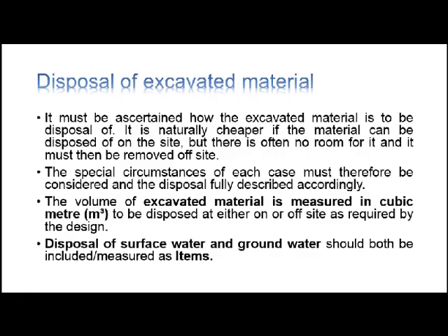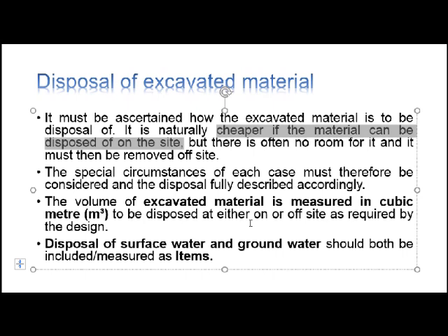So how about the disposal of the excavated material? This one relates to the trench just now. You should be certain how those excavated materials are to be disposed. Normally if you put it on site, it is much cheaper, but sometimes if there's no area to place that material, you might need to remove it offsite. That would cost you more. The rate would be different. If you put it on site, it will be a different price of disposal.